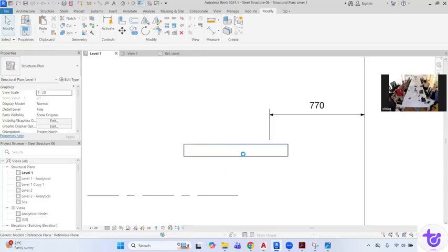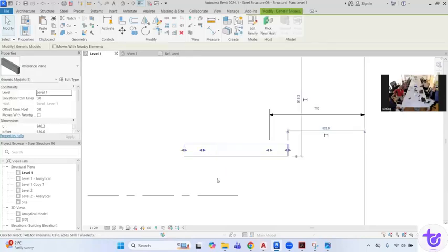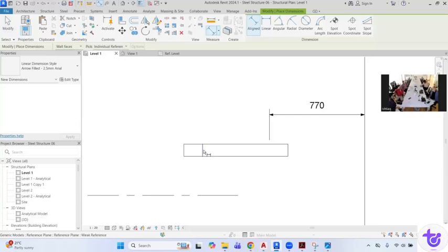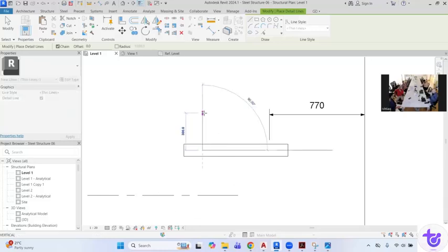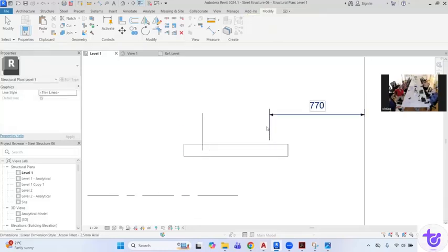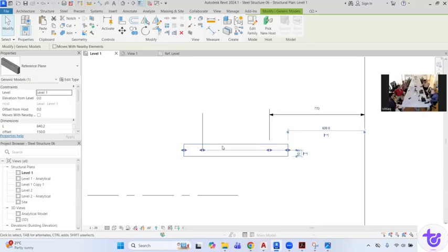So now you can see it will show both the sides. Also, you can put dimension. If you want to, for example, draw something with the reference of this reference plane, you can draw, so it will highlight. And if I change, for example, from the left side, the right one is also getting changed. Can you see it? If I increase or decrease, it is changing because both are bearing the same parameters, so both are changing. Yeah, that's it.